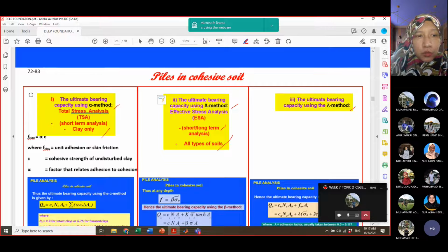It means that when we want to analyze the strength of the clay, whether it is in short-term analysis or long-term analysis, for total stress or effective stress analysis, you might be familiar with the strength parameters themselves. So talking about total stress analysis, it usually does not involve pore pressure measurement.